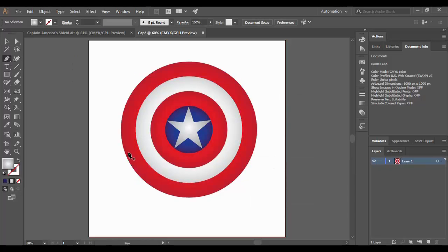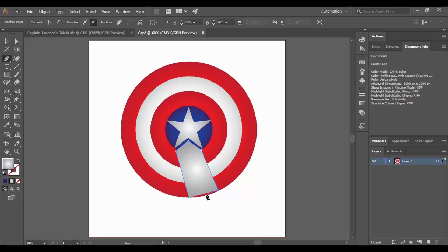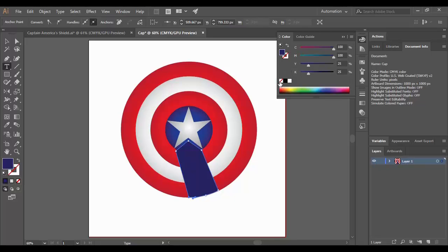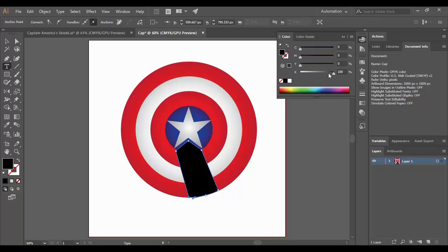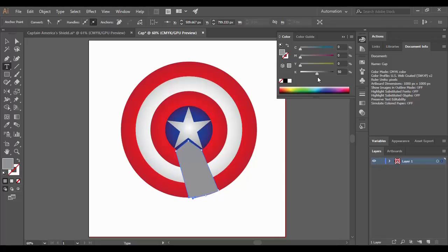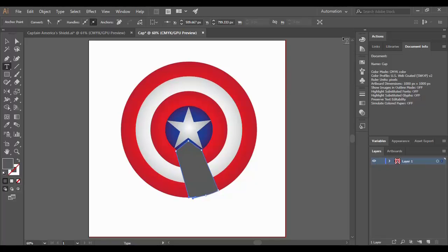Grab onto your pen tool again and draw these kinds of vectors that are tracing roughly the shapes of these stars, and it's kind of a shadow effect that is being added. Instead of the gradient, just apply a single color to it. Now, as far as the color is concerned, we are going to choose a shade of black, that is some kind of grayish color, like this. Then we are going to play with its opacity values a little bit.